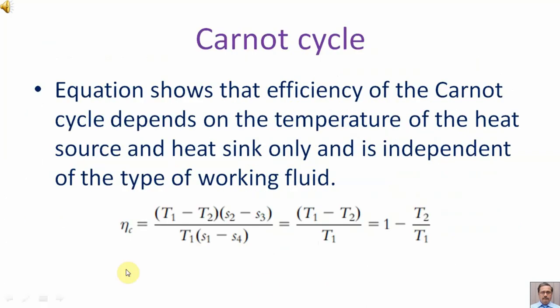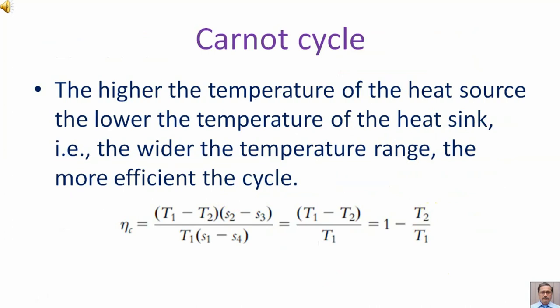Equation shows that efficiency of the Carnot cycle depends on the temperature of the heat source and heat sink only and is independent of the type of working fluid. Higher the temperature of the heat source, the lower the temperature of the heat sink, that is, wider the temperature range, the more efficient is the working cycle.